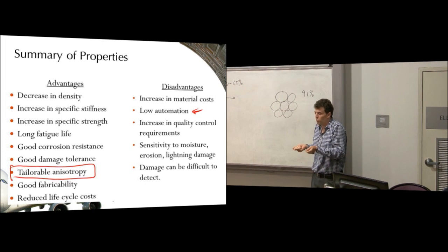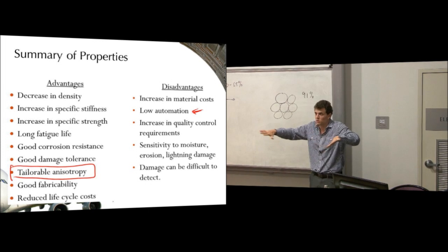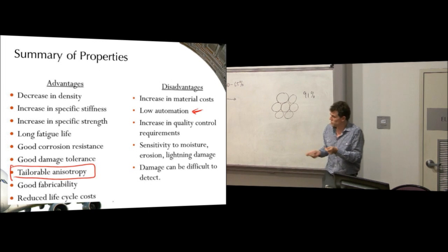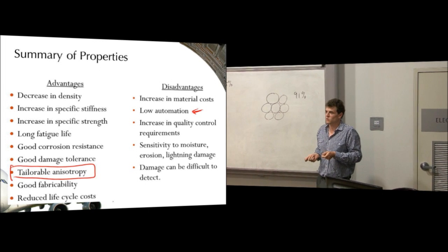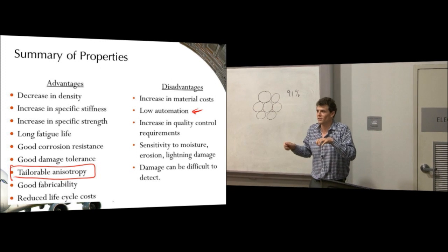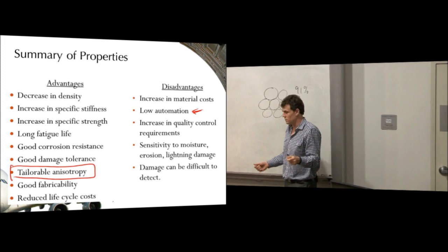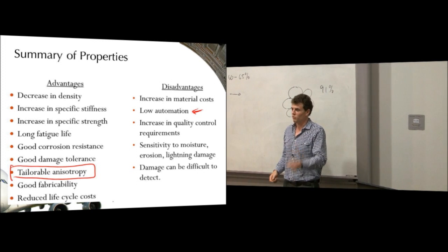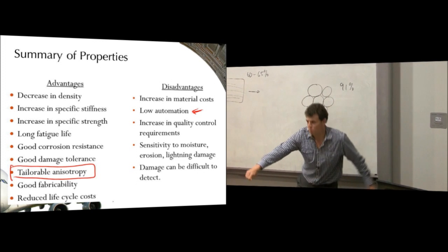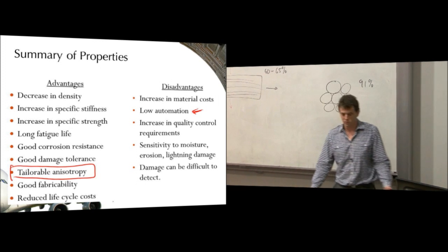An elevator for a 777 is many metres long and many metres wide, and you've got to get a big sheet. If you've ever stuck something like contact onto an exercise book, these materials, when you make an airliner out of them, are often pre-impregnated with resin, so they're a bit sticky so that they can stick into the mould. You've got to position a piece that's many metres across very accurately into a mould without it getting stuck and trying to pull it up and rearrange it. So you've got people on gantries and swinging from harnesses from the roof to try and get this positioned in a mould. So it was a very, very labour-intensive process to build composites.